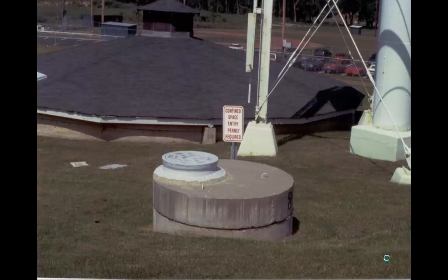And I've been asked, well, if the standard says that, how come Clayton doesn't have all their manholes labeled? Well, first of all, it's impractical to put road signs up in the middle of the roads. However, to meet the intent of the standard, one thing they have done recently over the last couple years is that the manhole covers that are new will likely have the verbiage stamped on it: danger, confined space.